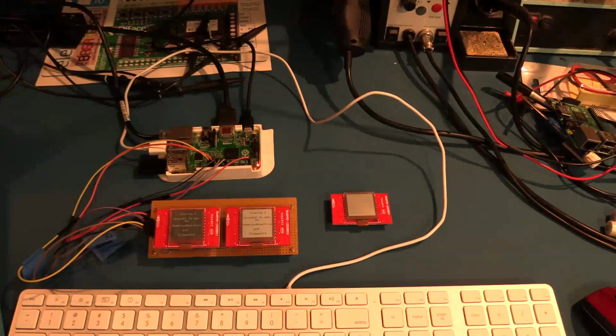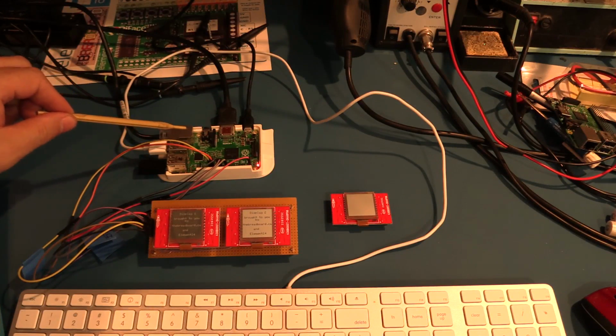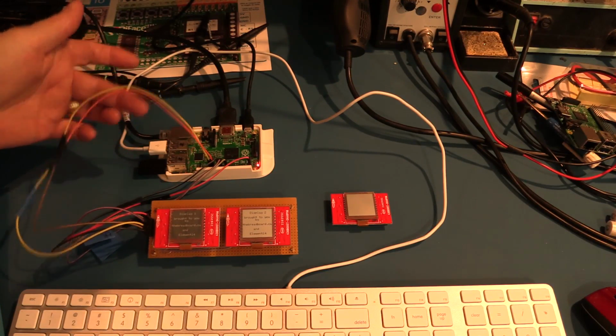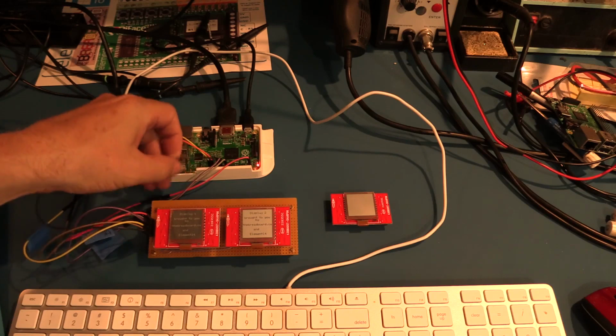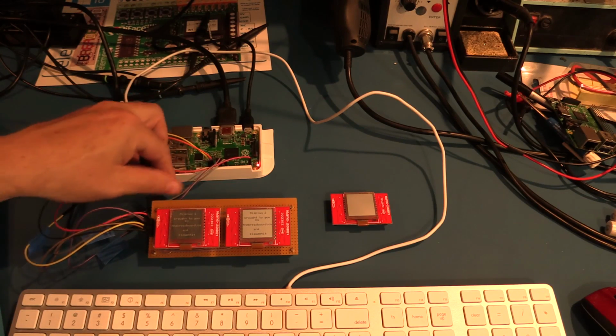So, anyway, let's go look at what I built to test this thing out, and we'll run you through the demo. So, what I have here, of course, is your standard Raspberry Pi. And I've got the 6 connections coming out. These 2 are the chip selects for each display. I've got the power, the 3.3 volts with the red one. The black one is the 0 volts.